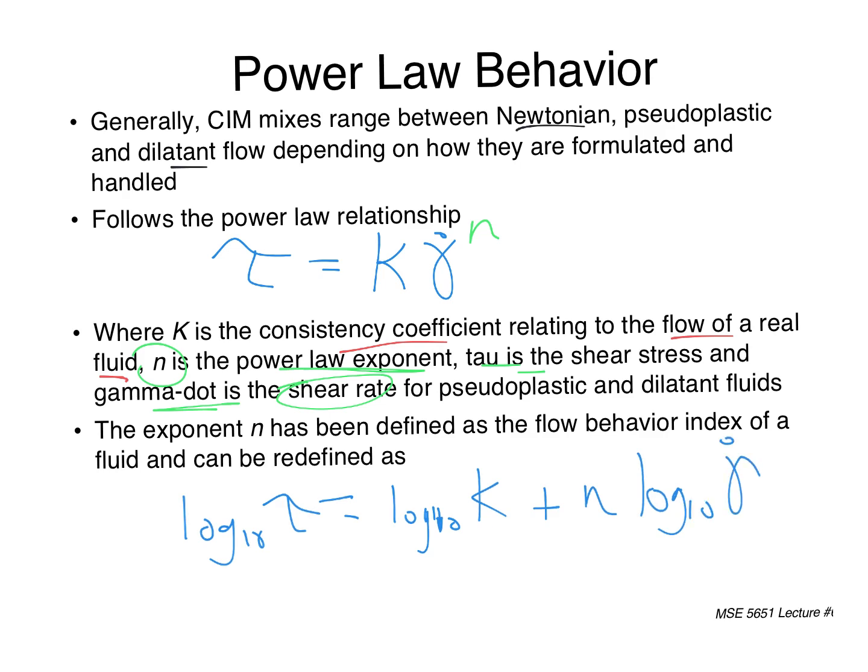All right. Those of you who may have done something like this in the lab would know that we would figure out the slope of a line based on experimental data. That's how we'd get n from this relationship, by breaking it down into the log-based equivalent form. So anyway, that's the governing relationship here, where a certain shear stress is required, and that translates to a certain shear rate in these systems. And n, of course, is very important to us because it determines how hard we have to work. Any questions about that?